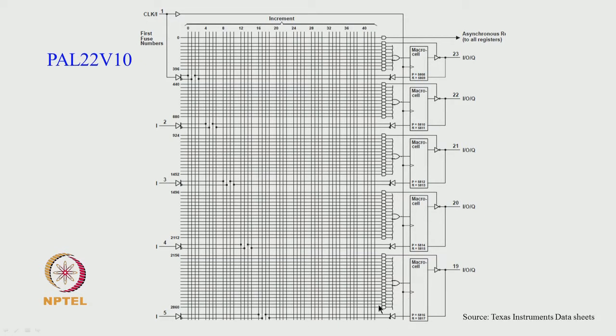So you will get 2 outputs, and that can be cascaded in the next section into 1 XOR gate, say 4 to 1, that is also possible. So you can think of various other schemes, maybe 3-input XOR gates, because a 3-input XOR gate when expanded will occupy only 8 product terms. So 3, 3, 2, which can be given to a 3-input XOR gate, and you get the output. So various possibilities are there.